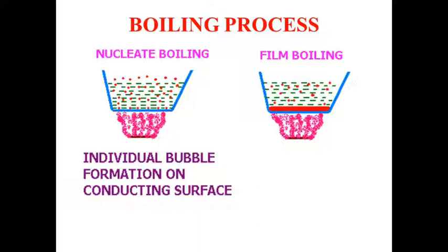In this way, gradually the entire fluid in the container attains the saturation temperature, and after that whatever excess heat is received adds up to the latent heat of vaporization, and gradually we find more and more tiny bubbles coming up, like nuclei, and they are coming up from the top, collapsing together, and gradually, as if from the top of the surface, they are flashing into steam.